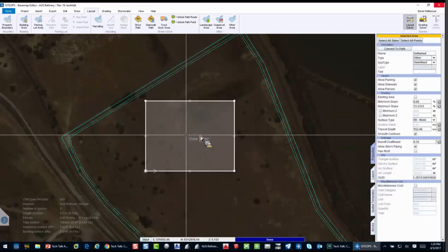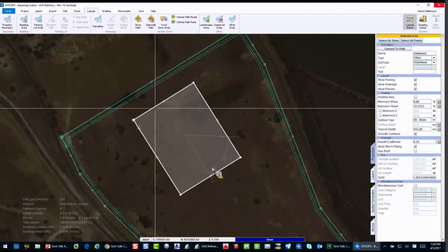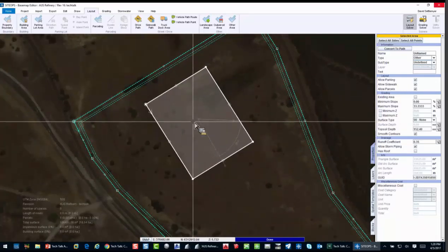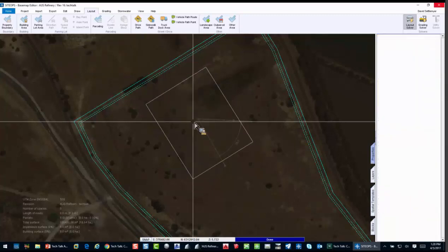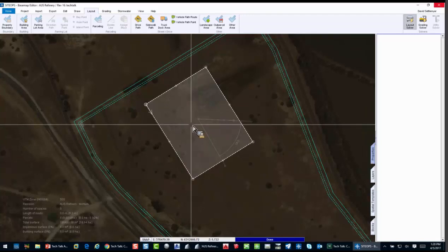I'm going to rotate this around. We're going to match it up, just like that. They wanted it roughly somewhere in this area, and we'll move it around as we get going. Then they needed a pit inside of this that would house the tanks. Again, we're going to sink that below grade. Part of this is being able to maneuver how far we go below to make things work. So we'll do another rectangle, and we'll make this one 60 by 54.